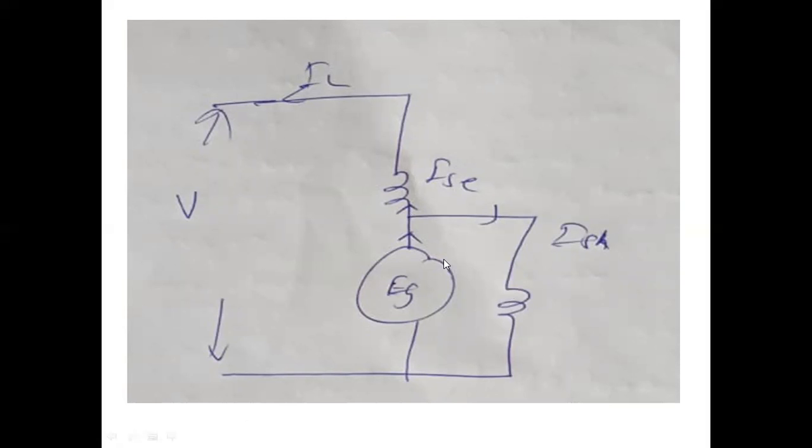This diagram, right? And you can say armature current IA coming out of the armature is nothing but IA equal to ISH plus IL or ISC. That is the same current. IL, load current, is the same as that of the series field current, right? So you have to consider both the drops. That's why this equation is also considering V plus armature drop. In the previous shunt case we only considered V plus armature drop, but here series field resistance is also there. So you have to consider that drop, plus you have to consider the brush drop because brush drop is also given.